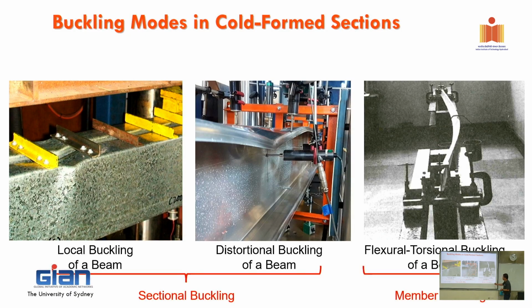And the last one is the member capacity. As I explained to you before, if you remove the row bridging, somehow, because you want to save a little bit of cost, you have to think about those carefully, whether you compensate a bit of strength, but you can save one row bridging. So something like that. So that's the other aspect of the design.